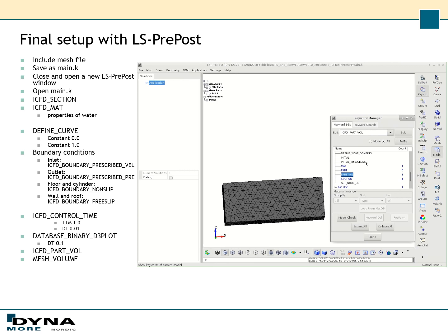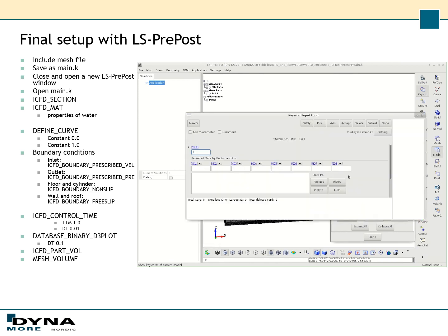And now we also need to define some mesh settings, and here, since we have provided a surface mesh, we need to tell the volume mesher how to create the volume mesh. So we go to mesh volume, and here all the parts will form the mesh, so just select all of them.